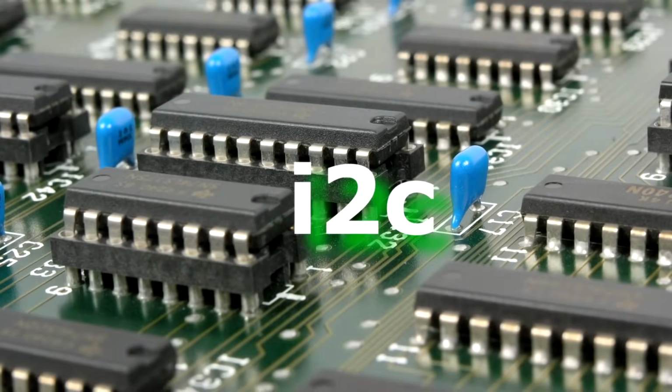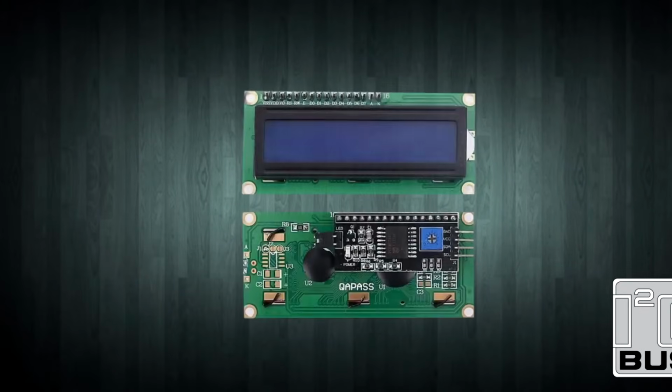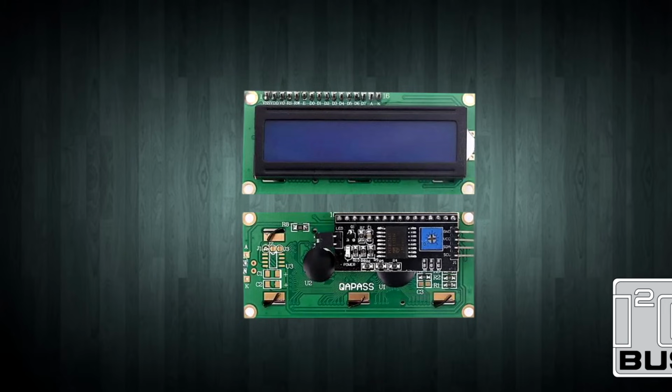Yes, my dear friend, in this lesson we will learn about I2C. It's especially important that we know the structure of the I2C protocol, because there is an I2C module on the LCD screen we will use. I2C is a serial communication protocol. Communication takes place over 2 lines. These are SDA and SCL. Both buses are bidirectional. That is, data can be sent and received.